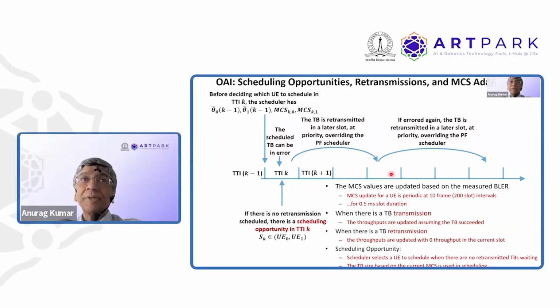It's already been coded, okay? And you stuff into that the URLLC bits. It's like an error for the eMBB, like having some bits corrupted. And what he's saying is that because of introducing URLLC packets into a coded eMBB slot, you get packet loss, a code block loss, and that causes this problem.